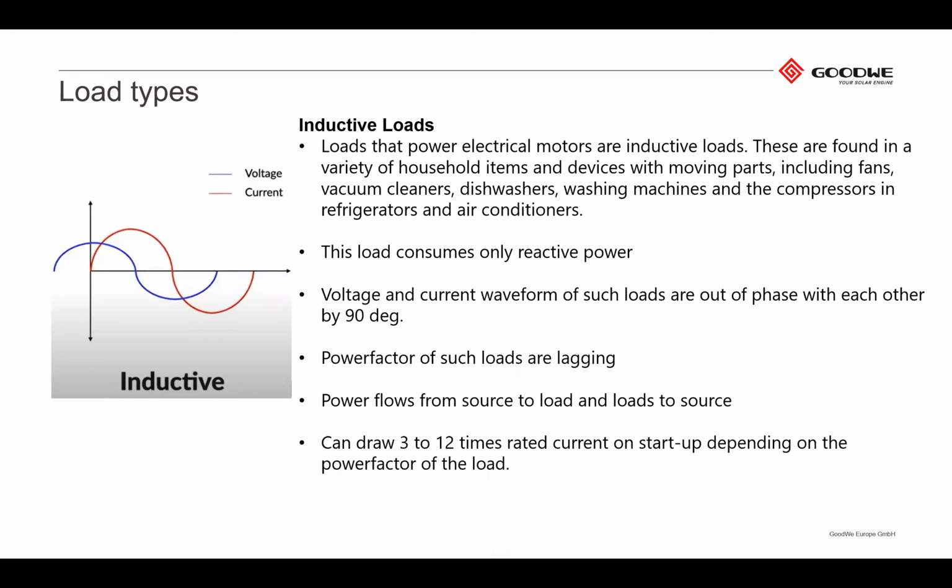In my experience, I have found this many times, that an inductive load causes a problem, especially when customers have smaller battery banks. Even something like a washing machine that is rated without elements at 500 watts, because its motor is a 500 watt motor, the power factor on the motor just caused the inverter to trip unless it had its full battery capacity. So it's very important to note this about inductive loads.